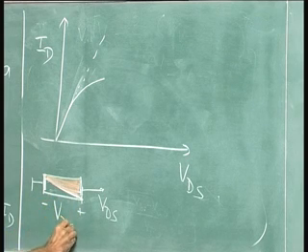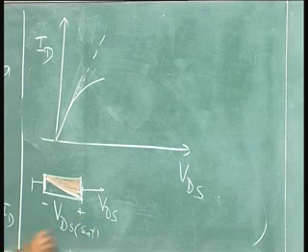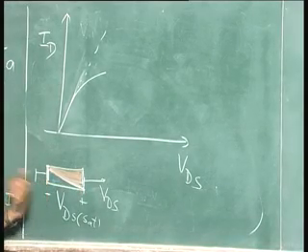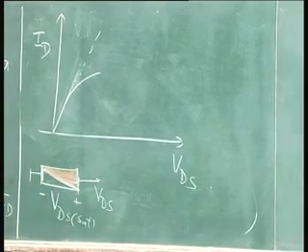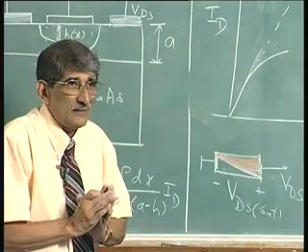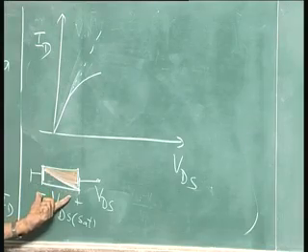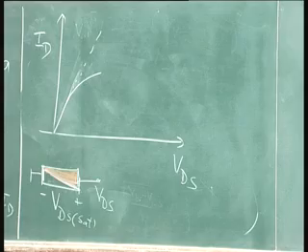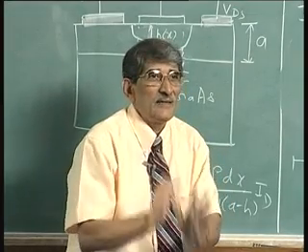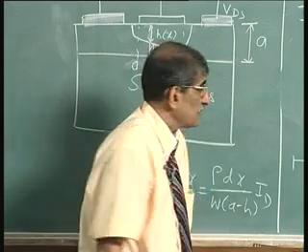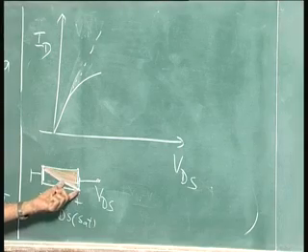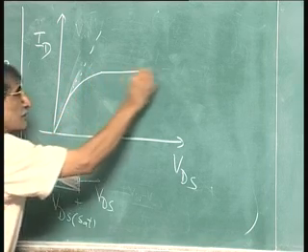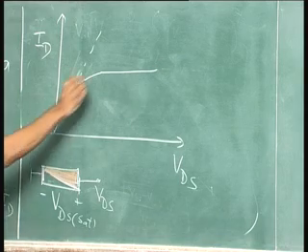That is V d sat, beyond that it will not increase. If this has saturated, what happens to current? We are still working on the theory of the resistor. If this has reached constant and the shape does not change, resistance does not change. So, the current is V d sat divided by that resistance. Still we are holding that law valid. So, V d sat, that voltage saturates, and since resistance also is saturated now, current saturates beyond that point, flat. So, this is actually V d sat.